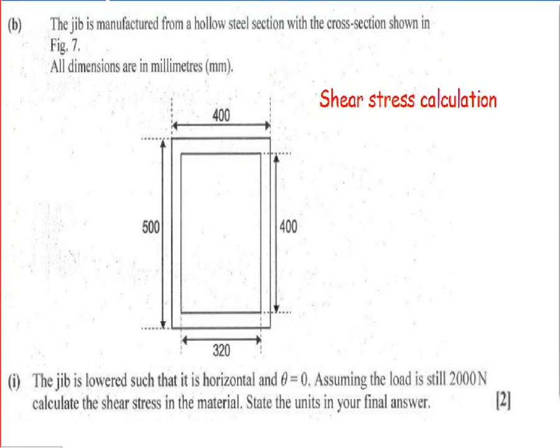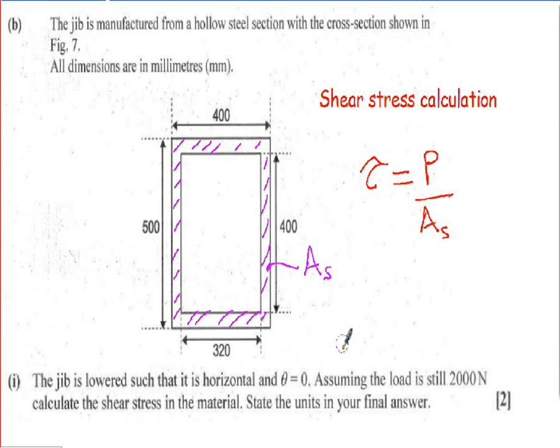Okay, we've got to work out the shear stress here. We have stresses for direct stress, stresses for shear stresses. If you remember from your formula, shear stress, I used to use that symbol, is the force applied to the section divided by the area that's in shear. Obviously the shear area will be this area here, which you will need to calculate. Calculate by sort of one rectangle, take away another rectangle. So that's the area that's in shear.